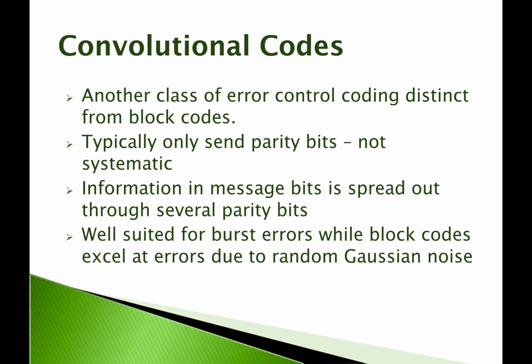And what's the difference there? Well, a burst error might be some interference, or you move through a deep fade where the radio propagation signal strength drops suddenly and stays down until you continue to move out of that faded area. That fading could be due to a cancellation effect, a destructive interference between two different signal paths to the destination, or it could be blocked by a building or a wall or something like that.